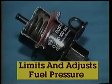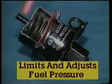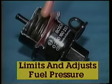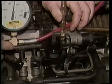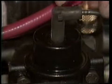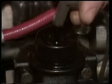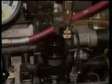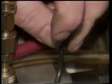A pressure regulator has the important job of limiting as well as adjusting fuel pressure with changes in engine load. To check the general action of a pressure regulator, remove its vacuum line while the engine is idling. This should affect engine operation slightly. As the vacuum line is removed, it should richen the fuel mixture and affect engine idle speed and idle smoothness. If nothing happens with the line removed, make sure vacuum is being fed to the regulator by feeling for vacuum with your finger. This provides a quick check of the supply line and unit.